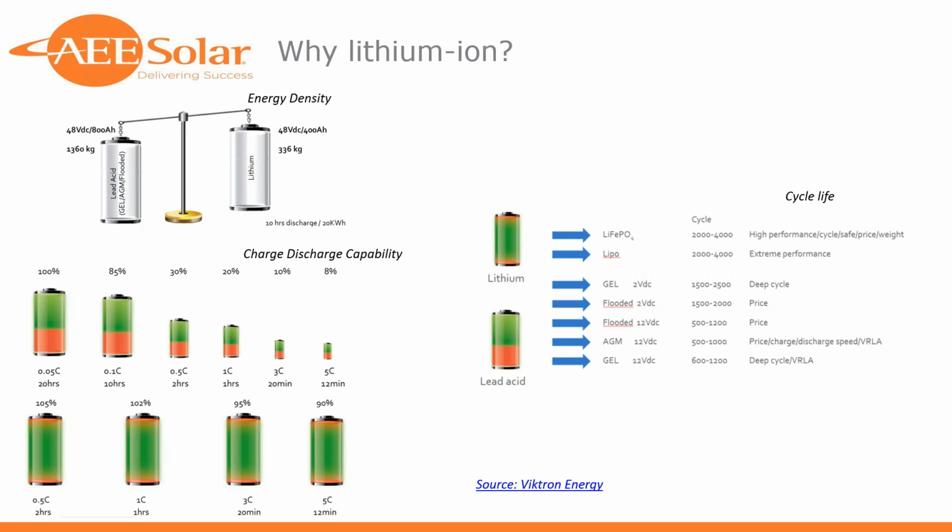There are 2 points here that I want to try to unpack for us. You see here the scale on the right, a lithium-ion chemistry, and I don't recall exactly which one he's pointing to, but I think the energy densities are close enough on LFP and NMC that it's kind of irrelevant. Basically, what he's got here is a 48 volt bus, 400 amp hours, without packaging, if you will, without converters and things, 336 kilograms.